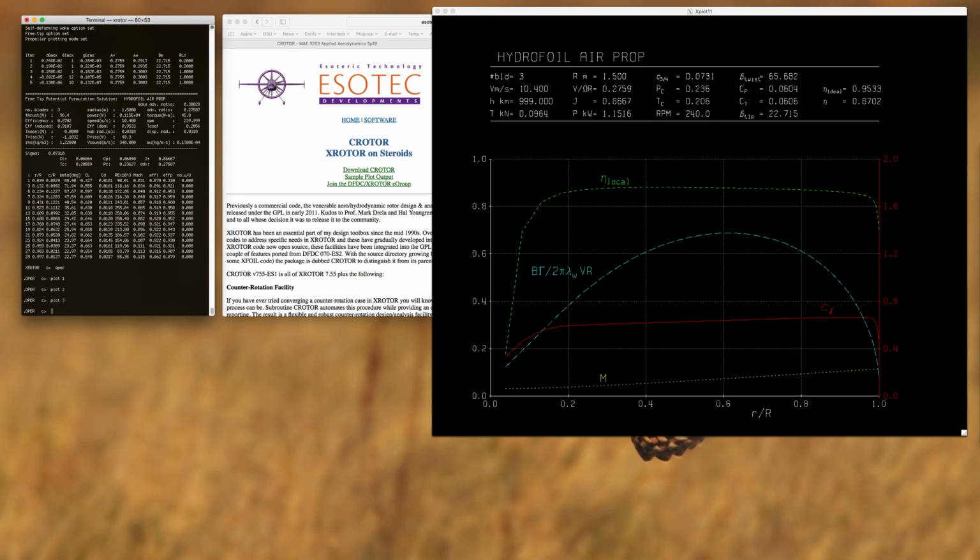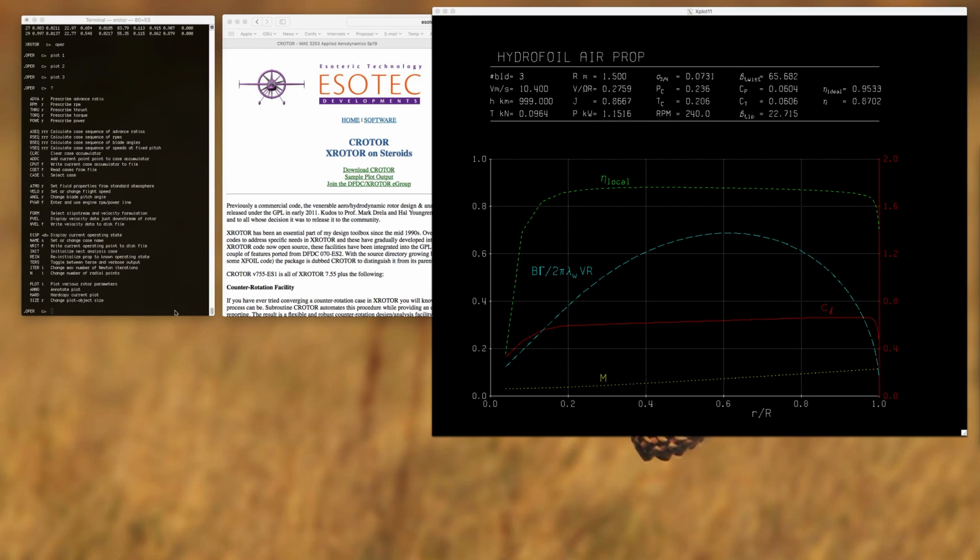Now, propellers are pretty complex things, and it's pretty difficult to essentially make one propeller fit a wide variety of conditions, and that's why we obviously have things such as constant speed props or variable pitch props that allow us to go through the process of changing those angles. In this particular case, we can vary things such as the basic operating parameters, such as changing the blade angles.